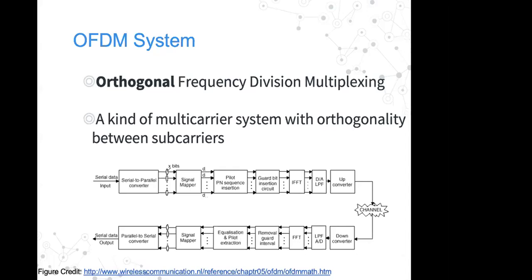This means we need strict orthogonality between the subcarriers. No one will guarantee that your system will give you strict orthogonality. Even if your electronics are perfect, and even if the ambient temperature is working in a quite natural way, there is always a problem of intersymbol interference and intercarrier interference.